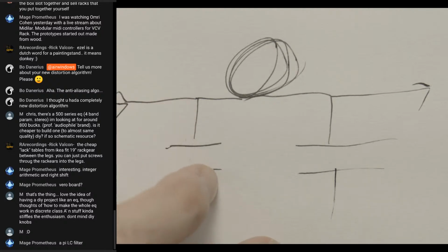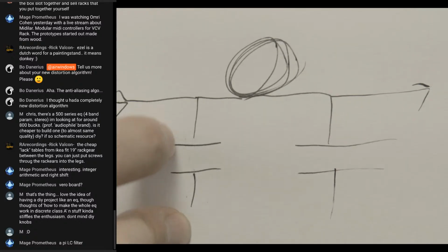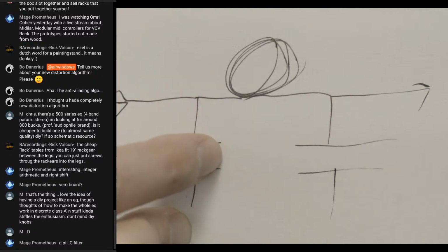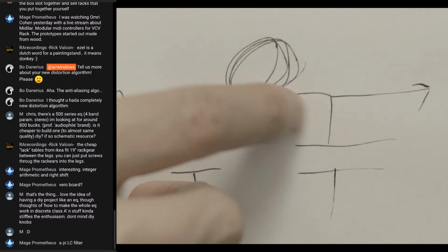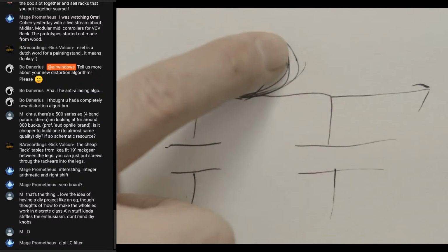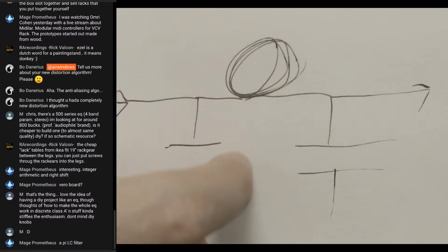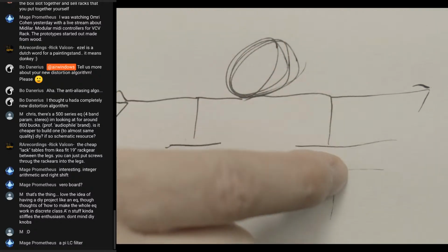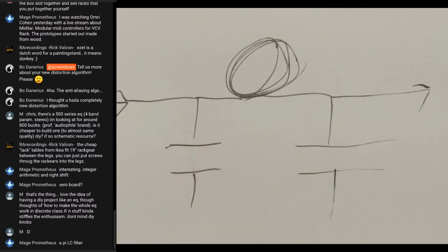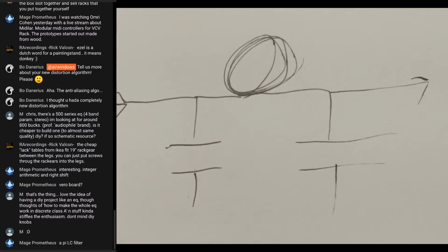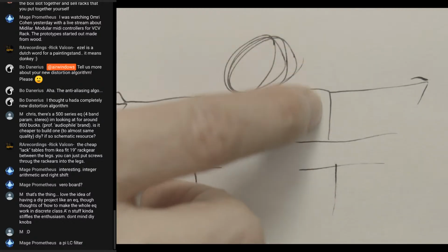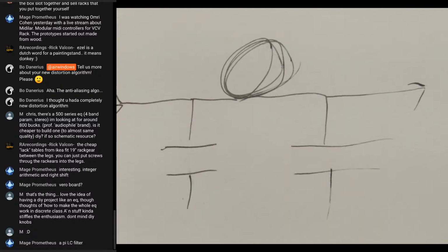But in this case, this circuit is a super effective low pass. Having the one capacitor makes it 6 dB per octave, if I'm not mistaken. And each additional part, like the inductor, blocks highs, so that's also contributing to the steepness of the filter. The other capacitor rolls off more highs to ground, which is down here. That also increases the steepness of the filter and brings the frequency down a little bit.